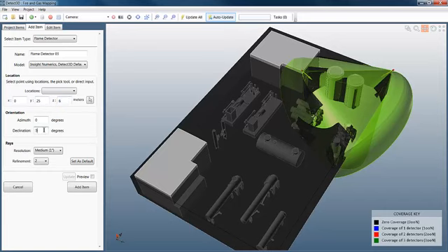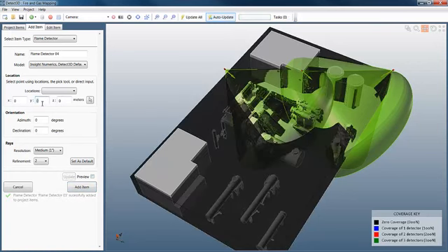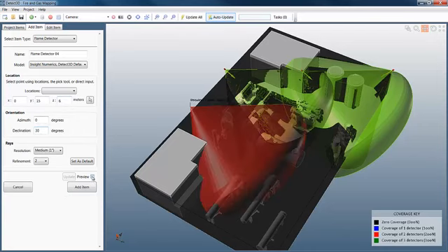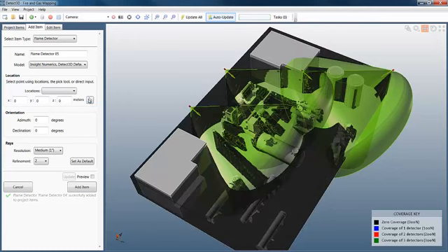Okay, so let's put one at this manual location here. Looks good. I'll enter the coordinates for the second one. You can see the 0 visibility isovolume automatically updating, which is really nice because you can just go through the fire zone, adding flame detectors where you see blind spots, and come up with a very good layout very, very quickly.